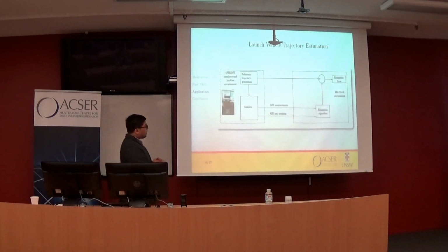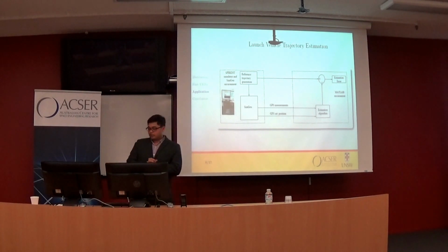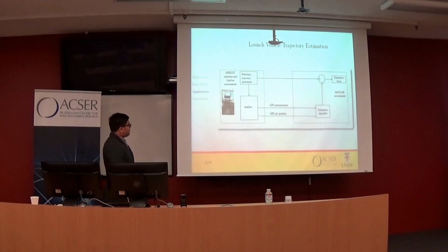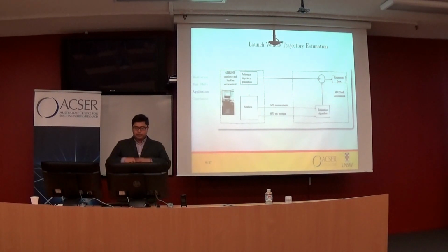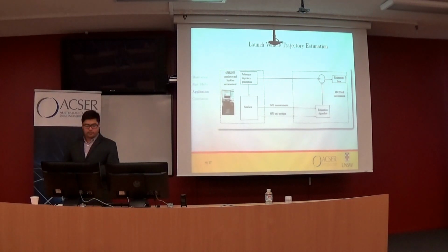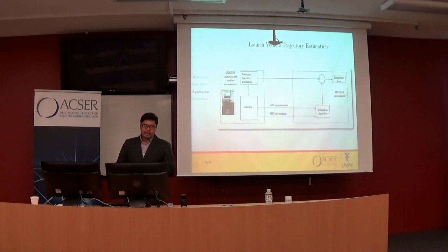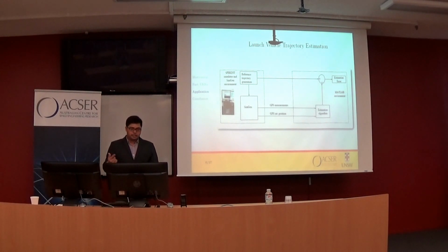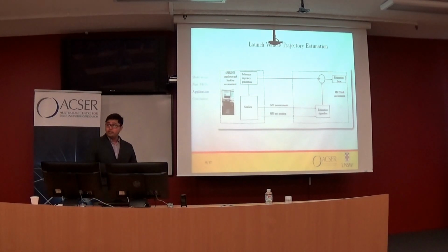So how do we simulate? Because we can't have a launch vehicle and test it, we have to simulate everything. So what we did was build a model of the launch vehicle in MATLAB and propagate it by integration, and that we considered as the reference trajectory.